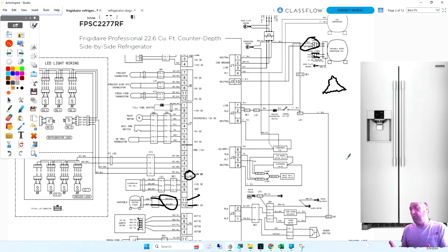And then if I don't open the compressor box, hopefully I can just return it to the parts house and say, oh, the customer canceled on me, and get my money back for the compressor if I don't need it. But if I change the inverter and it still doesn't work, I'm going to change the compressor too and tell the customer, listen, we've got to change both of these. Your compressor's bad. This is all part of one assembly, and I'll get my money for my parts.